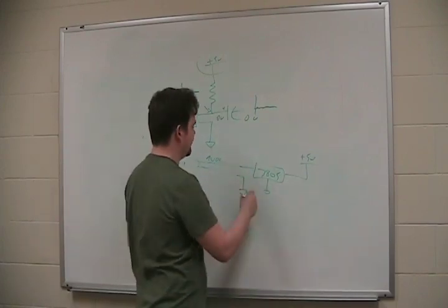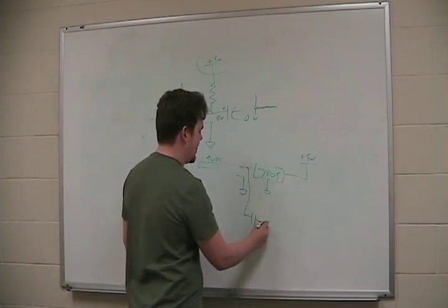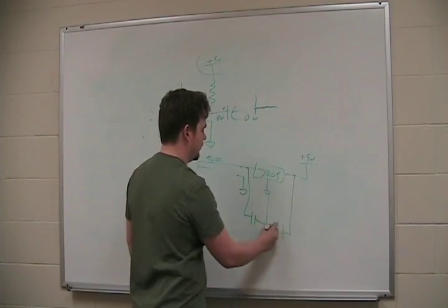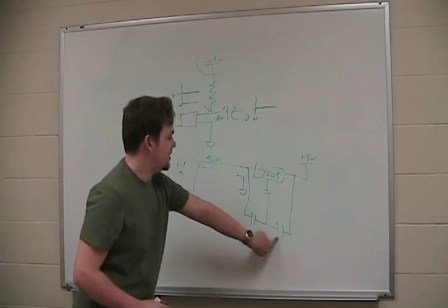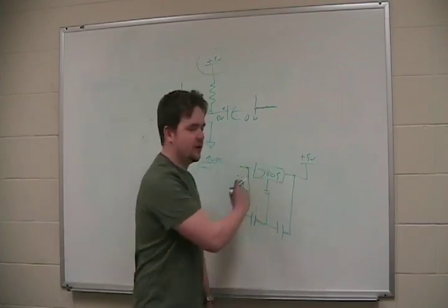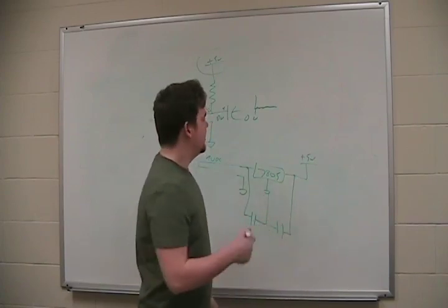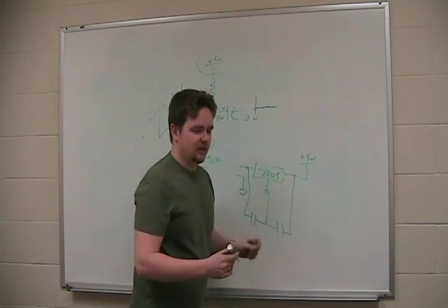So what we're going to do is take capacitors, very small ones, with very small values, and connect the input and output through the capacitor to ground. It basically acts as a filter. It filters out all that extra noise. Not all of it. Noise is never eliminated, but it filters out a lot of it. So it just makes this 5-volt signal a lot cleaner.